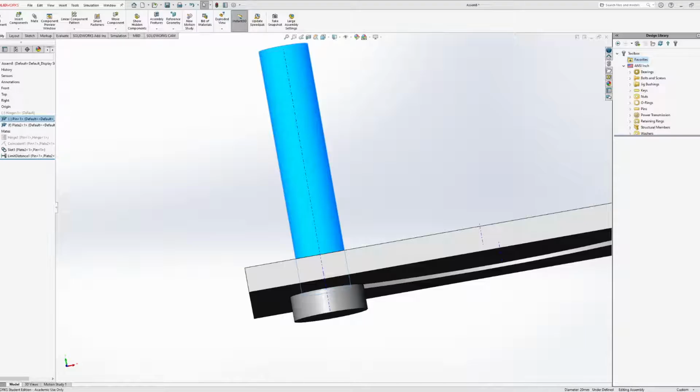I think what I would primarily recommend is try to do a limit distance between the two things that it's supposed to be between, or rather between the thing that can move and the thing that can't, and then play around with the numbers appropriately, such that the left-hand side, or rather the front of the yoke, is going to hit one screw, and the back of the yoke is at best going to hit the other screw if you pull it all the way over there.